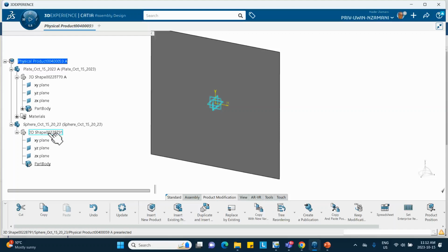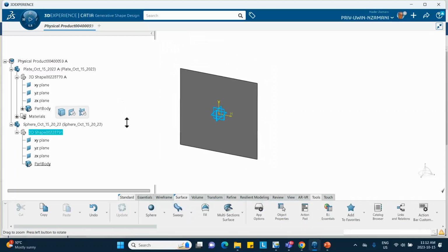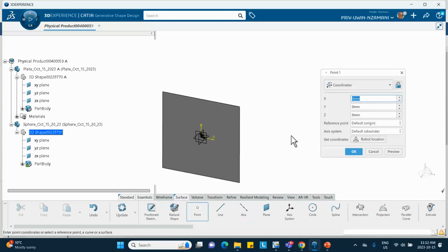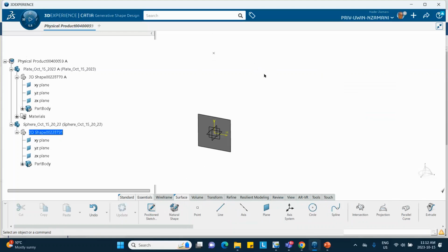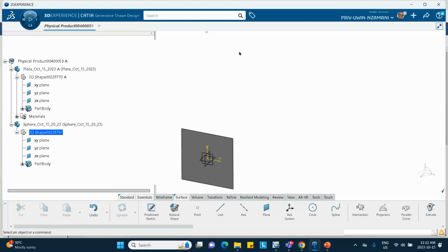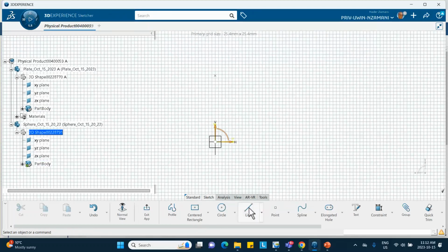Double click on shape, 3D shape. The way I did this in tutorial 7 was I created a reference point up there, because remember, analytical rigid surface needs a reference point. So I'm in that part. Let's go to essential. Let's create a point, and the point is 500 millimeter up, and it's there. You can see that right there. What I then did was to draw a line at 45 degrees and put the sphere at the end of it. So on this vertical plane, I sketched, okay, there is that point that I drew. I drew a line here.